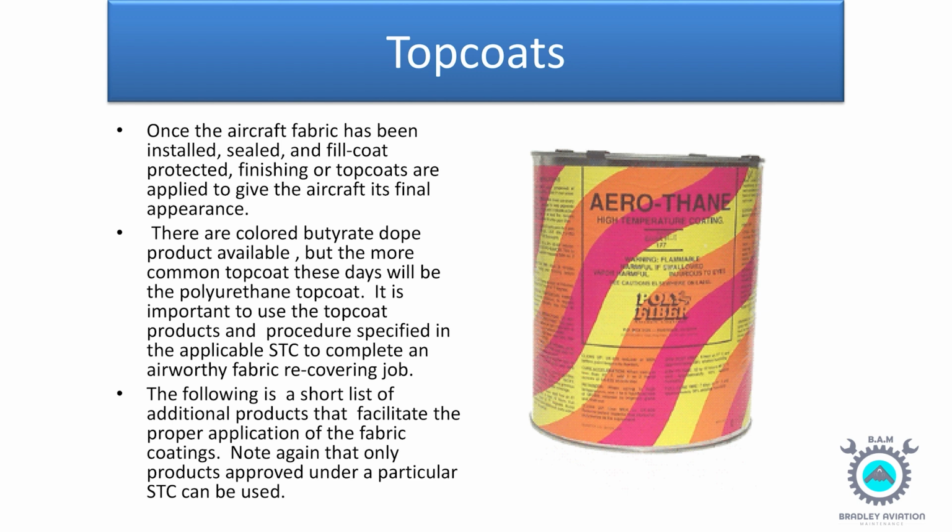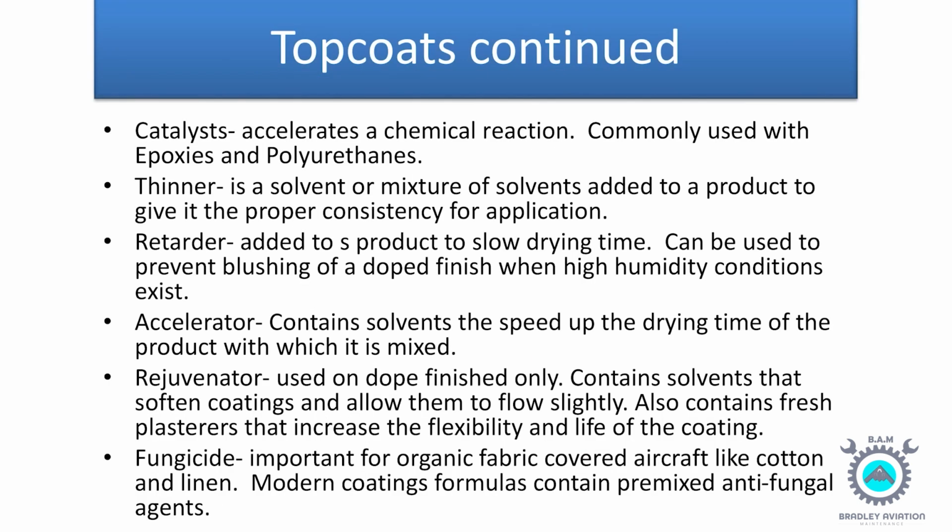airworthy fabric recovering job. The following is a short list of additional products that facilitate the proper application of the fabric coatings. Note again that only products approved under a particular STC can be used. Top coats continued. Catalyst accelerates a chemical reaction, commonly used with epoxies and polyurethanes. Thinner is a solvent or mixture of solvents added to a product to give it the proper consistency for application.